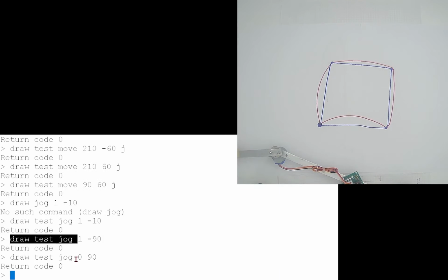So there it is. And it's pretty clear that moving in joint space doesn't give you straight lines in Cartesian space. And so I think that's what you would expect. And so that's the end of the demo. I think what this demo has showed us, if you're building a drawing arm with this design, these two joints, and you're using $2 motors, you shouldn't expect high precision. But it is a way to learn about robotics and kinematics. And so for that, it's just fine.